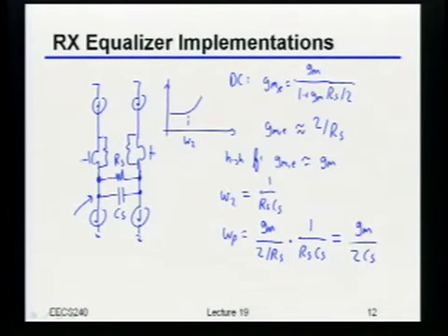Unfortunately, if RO is not that big, then whatever you have sitting at that output over there is going to interact with what's happening down at the source over here. So all of the nice equations I've written here, just be warned, you have to be a little bit careful. Because if you don't have really great RO, you can get some, let's say, interesting phenomena happening once you try and build the thing. But you guys will get the chance to see that.